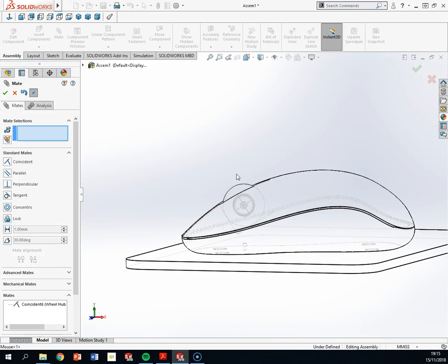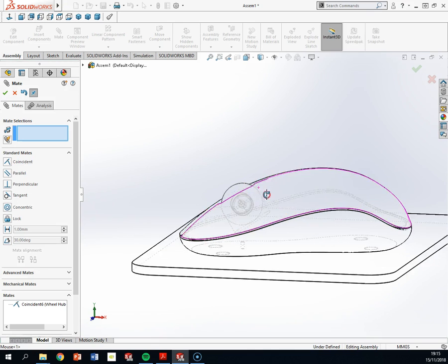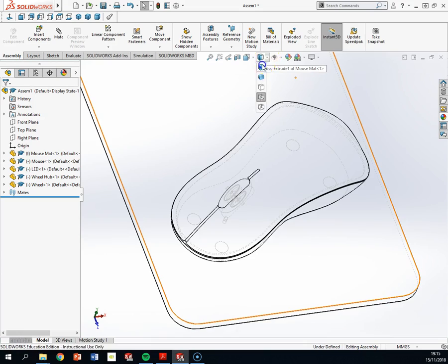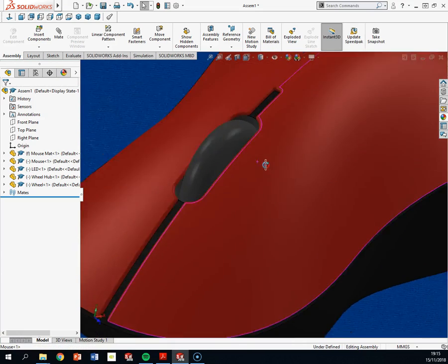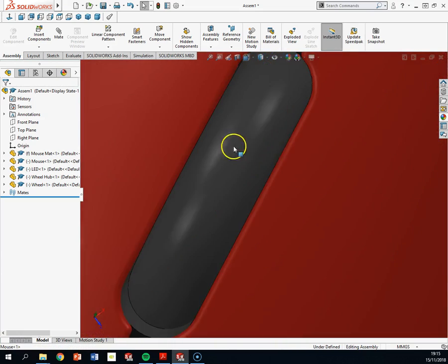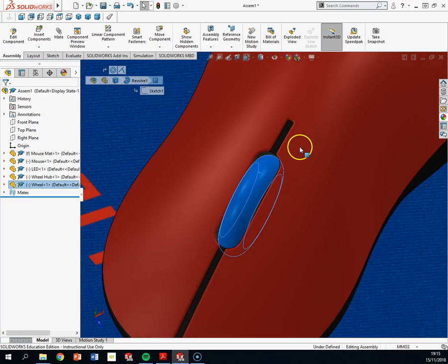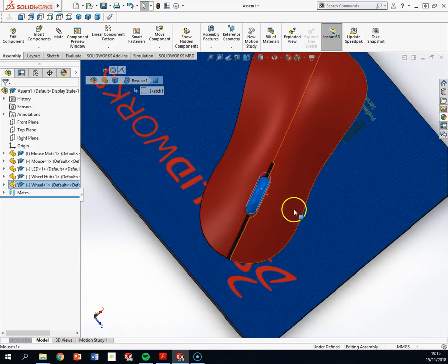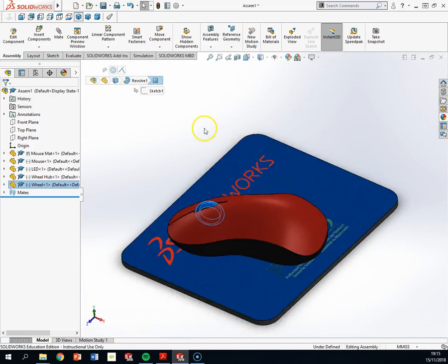So you have to make sure things like that, there's enough clearance for components. I'm not going to do it now, but I could go back and make this wheel's diameter slightly smaller or the slot slightly bigger. There probably needs to be a little bit more clearance width-wise as well in it there. But that's pretty much it there.